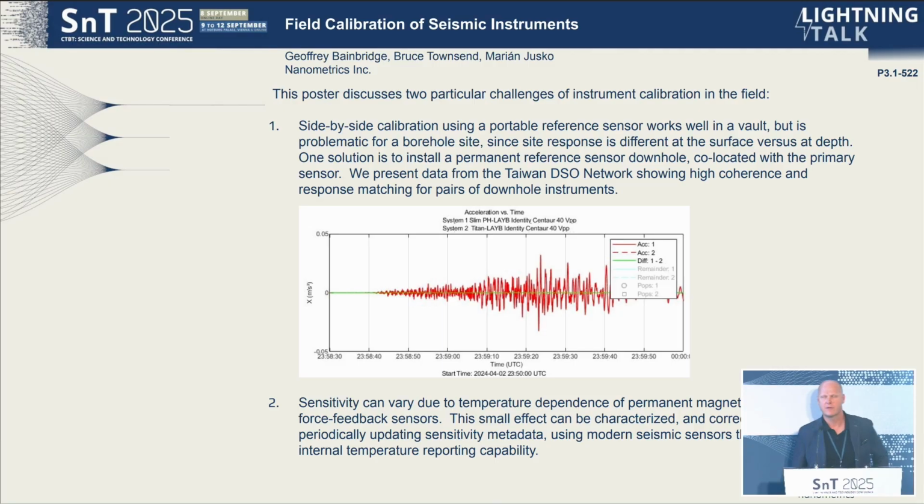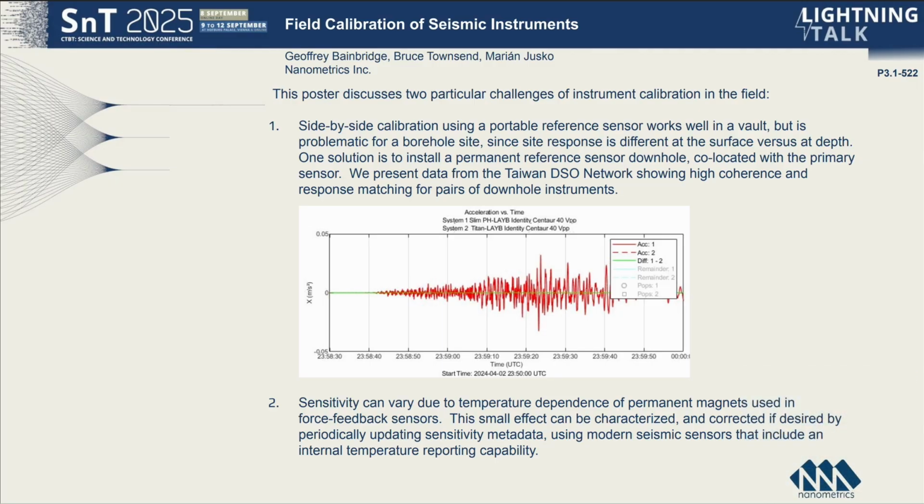Hello everyone, I'm Marian Yusko from Nanometrics, and our poster deals with the field calibration of seismic instruments. While obtaining initial calibration in a lab environment is a fairly straightforward process, it becomes more involved when we try to validate the seismometer performance in the field. One could argue that conducting field calibration using a reference sensor is viable at surface installations. It becomes more difficult when the operational sensor is downhole in a different environment, at a different depth.